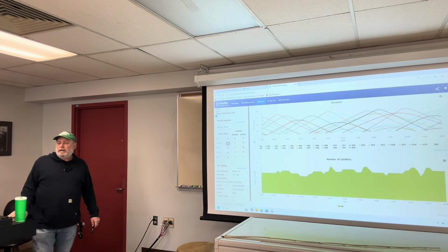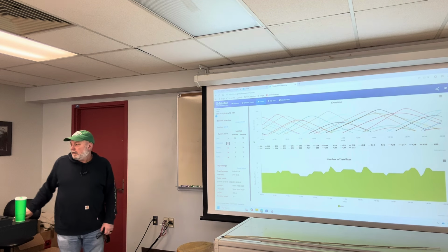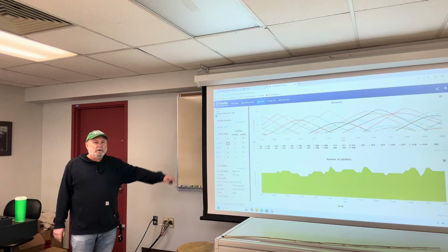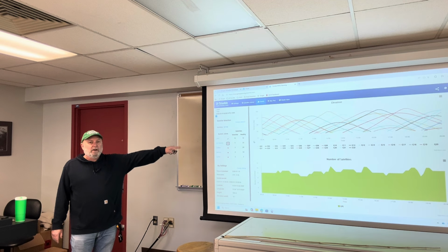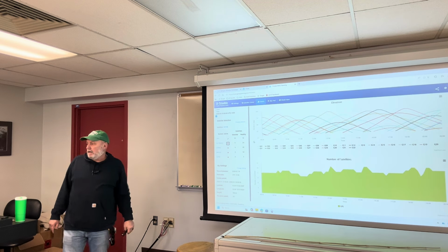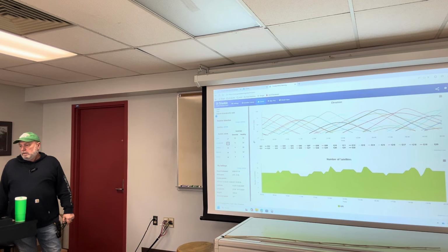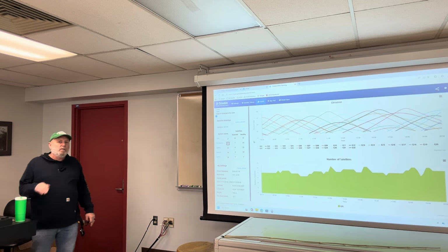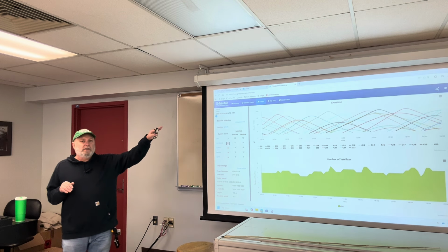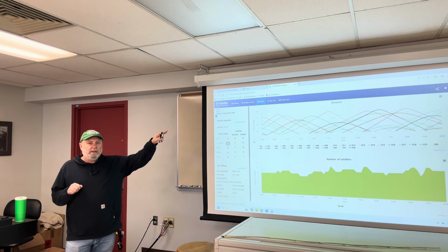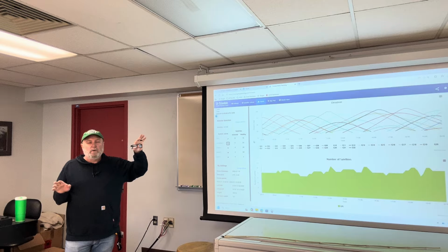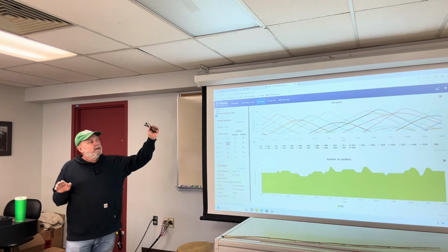The elevation here has to do with the degrees from the horizon, so your horizon being 0, going up. You do not want to use satellites that are very close to your elevation mask. You want to be careful with them, I should say.